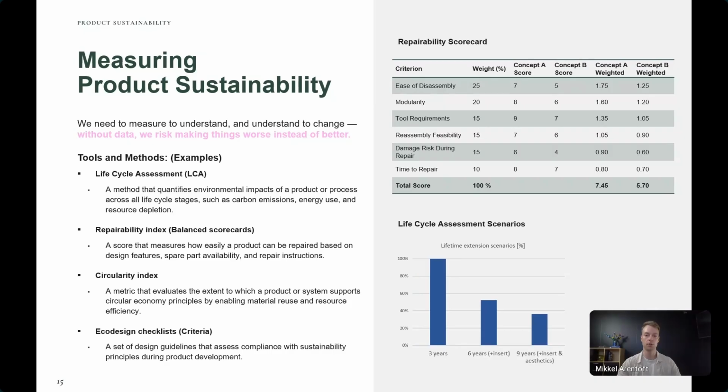Currently, when you select a material, you compare the price to ensure that it meets the target cost price. In the same way, you can consider the emissions factor, the CO2 per kilo of material, and compare alternative designs in that way. In the same way, decisions on joining methods will significantly impact both repairability and recyclability, which are key circularity parameters of your product. The disassembly, repairability, and recyclability are also measurable factors based on the performance on a given set of criteria, for example.